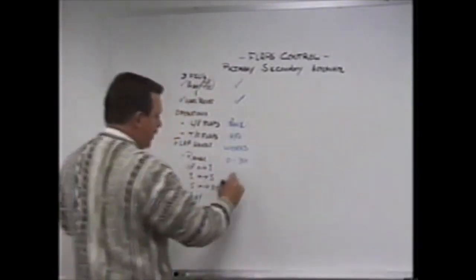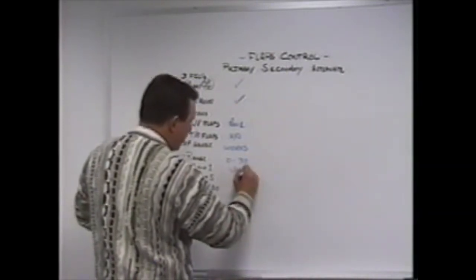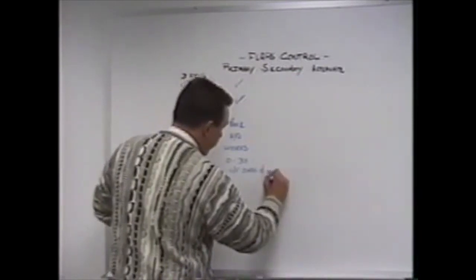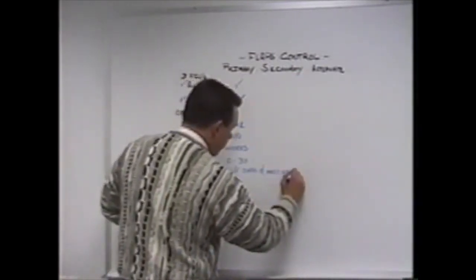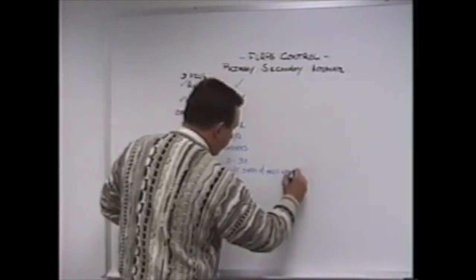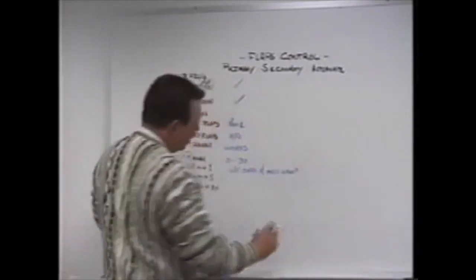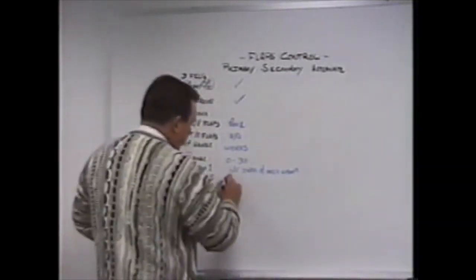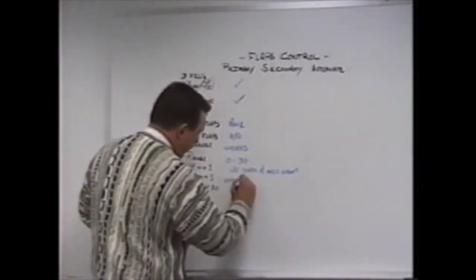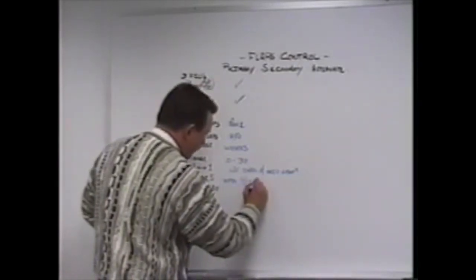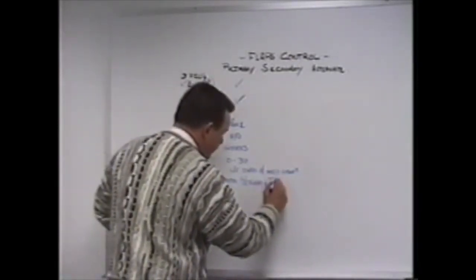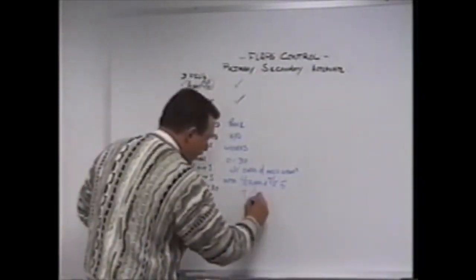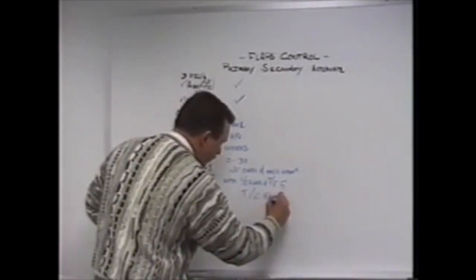When you go from flaps up to 1, you get leading edge, inboard, and mid-span. There are no trailing edge flaps at flaps position 1. It's all leading edge, well, partial leading edge. The inboard and mid-span come out. When you go from 1 to 5, the outboard leading edge flaps come out and trailers go to 5. Flaps 5 to 30 is trailing edge flaps only.